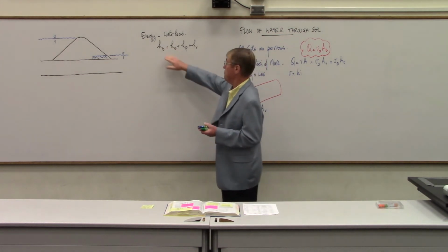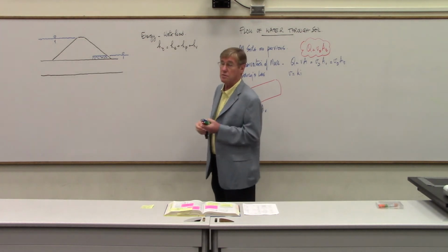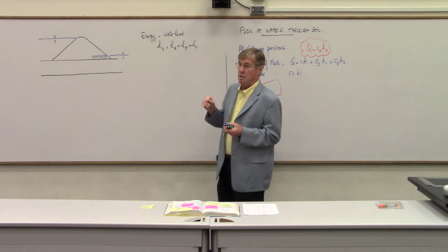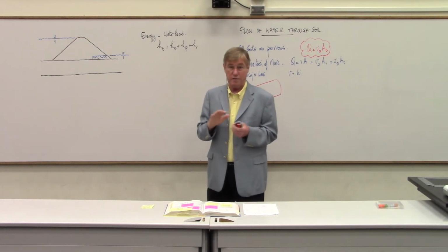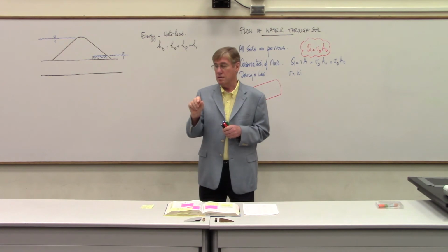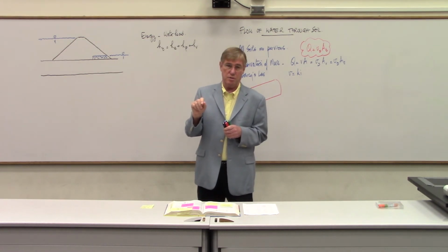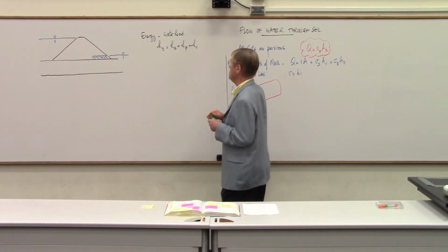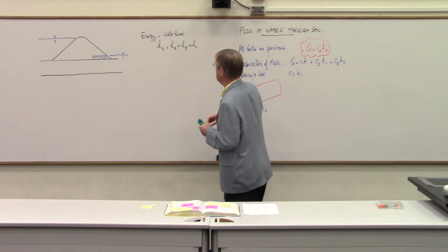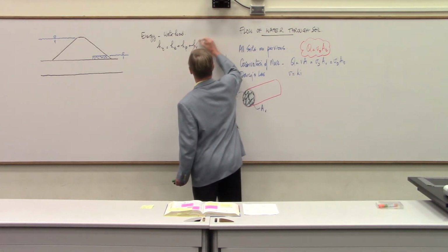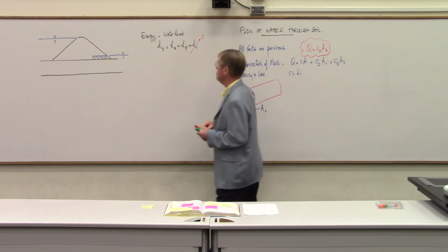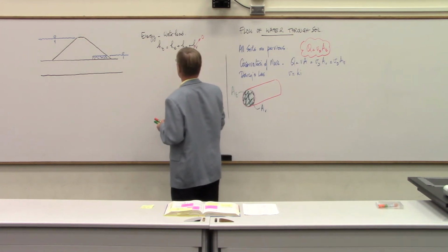So that's, if you have energy and you want to drive somewhere, you're going to burn energy through elevation, pressure, and velocity. In soils, the water goes very slowly. You will see that we're talking about a fraction of centimeters per second. And so it's going very slowly. So we don't lose much energy in terms of velocity. So we're going to ignore this part right here. We're going to set this one equal to 0. So the first thing to remember is that the total head is the elevation head plus the pressure head.